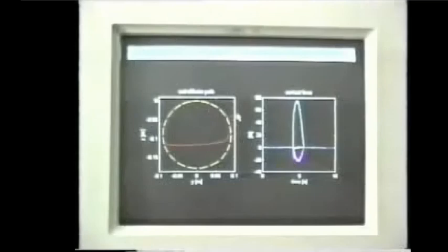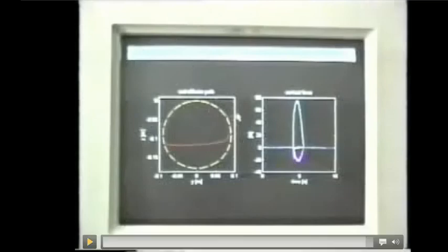In order to have this behavior, we should be sufficiently compliant, but not too compliant in the choice of our model. So have a stiffness parameter which is not low. Otherwise, we would not trace correctly the circular path in free space. But if we are too stiff, then we will tend to enter the surface and apply large forces. And you see that the forces that arise in contact are shown in the second plot on the VCR.